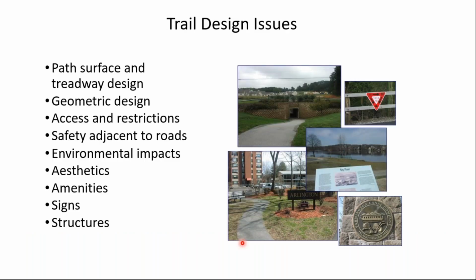Some of the trail design issues: the path surface and treadway design, how wide, what surface type are we going to use? Geometric design, the curves and grades, what sort of access and restrictions are we going to have? If the path or trail is close to the roadway, what special provisions do we need at intersections? What about environmental impacts, aesthetics, amenities? Could be things like signage, benches. We see a bench here along the trail. I would call these amenities.